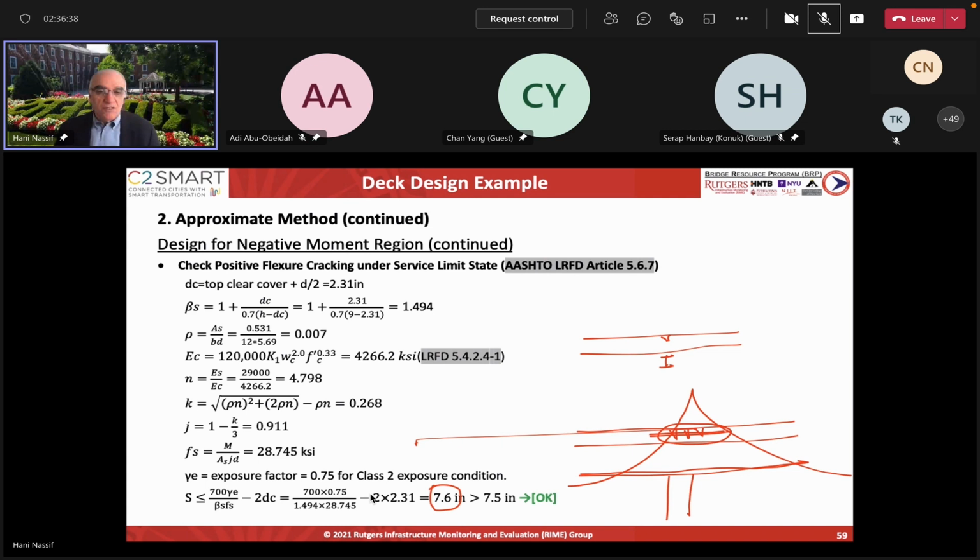But if you double or triple the reinforcement, once corrosion compromises that place, it will corrode all the same way. But there are many details, they call them continuity details, that have been designed to make the slab not crack, basically. So you could do a different post-tensioning technique, different detailing, or allow some link slab that has very high capacity there, or things like that. So this is a different problem than this type of problem.